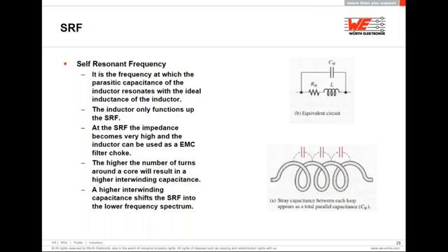The self-resonant frequency, or SRF, is the frequency at which the parasitic capacitances of the inductor resonate with the ideal inductance of the inductor. The input energy oscillates back and forth between the elements of inductance and capacitance. The inductor only functions up to the self-resonant frequency.